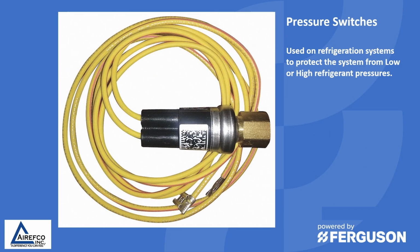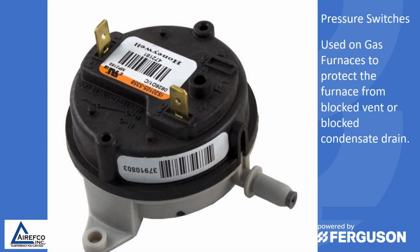On the refrigeration side, safety switches are like these pressure switches used on refrigeration systems to protect the system from low or high refrigerant pressures. Another type of safety switch are these pressure switches that are used on gas furnaces to protect the furnace from either a blocked vent or a blocked condensate drain.